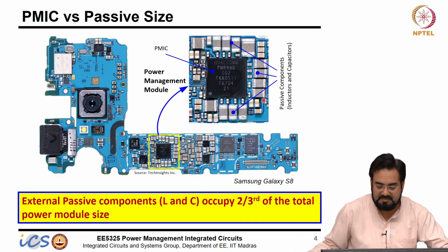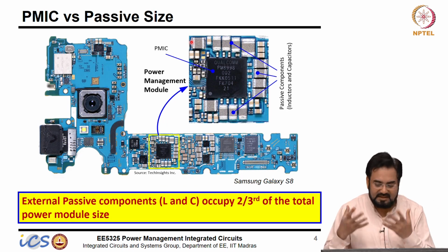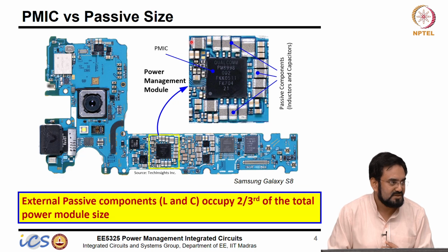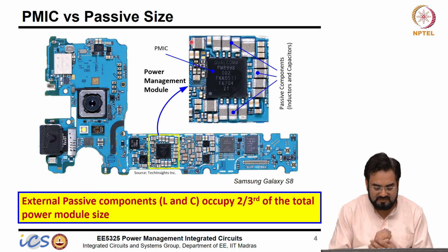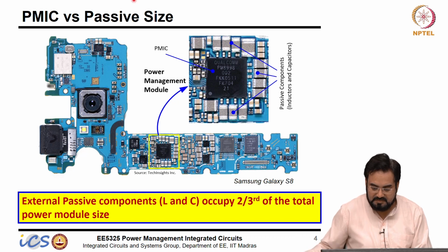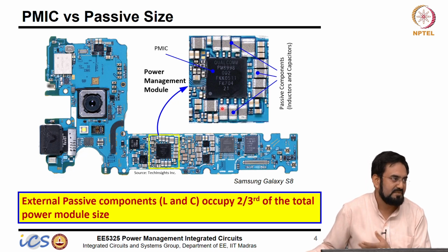And this is a much bigger PMIC, because it has integrated, let's say, 5 to 6 switching converters, then it has more than 25-30 LDOs inside. So you have a lot of power supplies inside, and other than that you have a lot of housekeeping stuff like ADCs, everything for measurement. So it's a more than 200 pins PMIC, you can say.